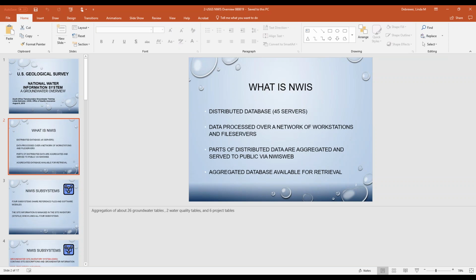No, I did hear the question. She asked about lessons learned. And I think it's a very good question. Lessons learned really include things like the type of data that you're collecting, to make sure you consistently collect things like your measuring point, your land surface datum, the locational information about your site.